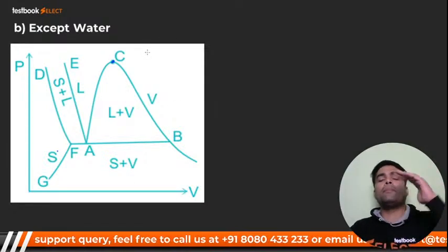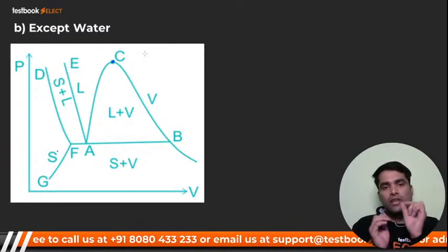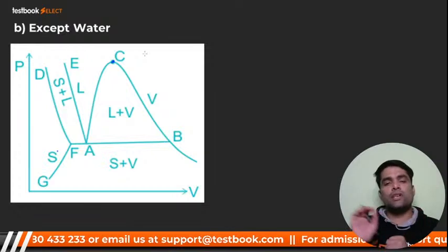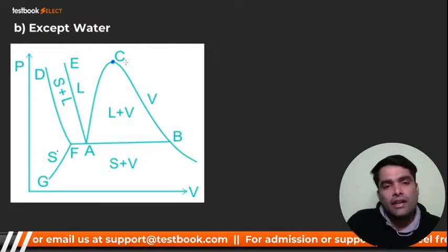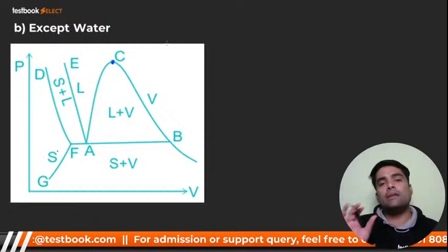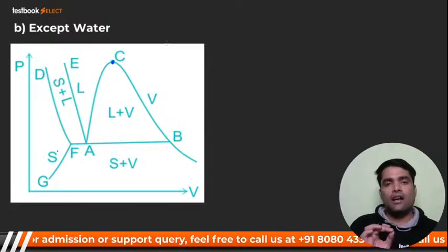So as you move to the upper side, what will happen? The heat required, or the energy required, for the phase change from saturated liquid to saturated vapor reduces, and at the critical point it will become zero. That means above the critical point the liquid is directly flashed into vapor without any energy. Right, I hope you got it.